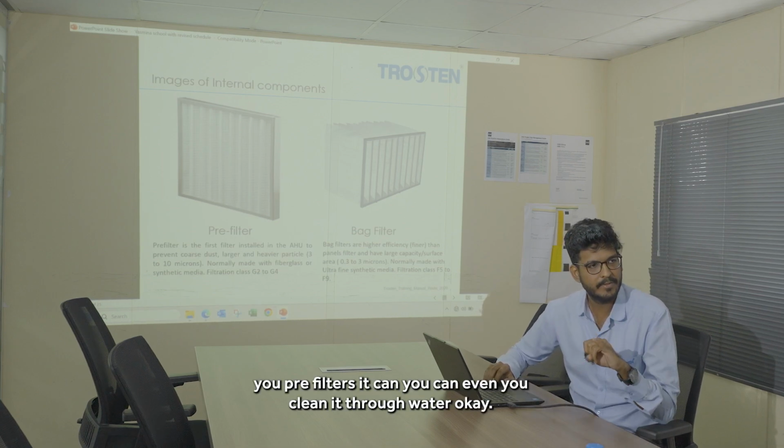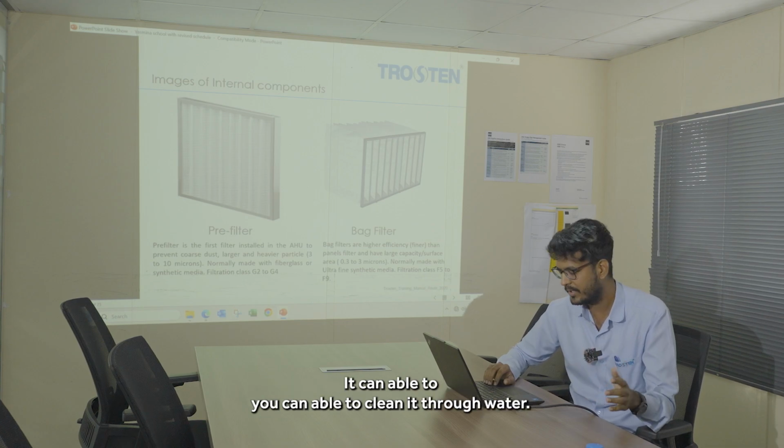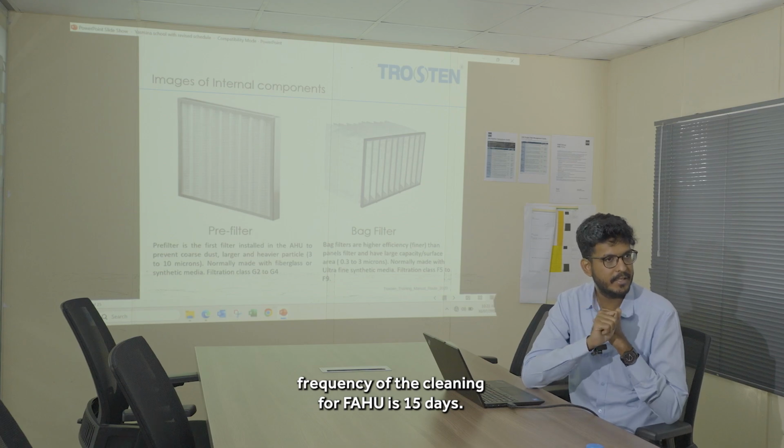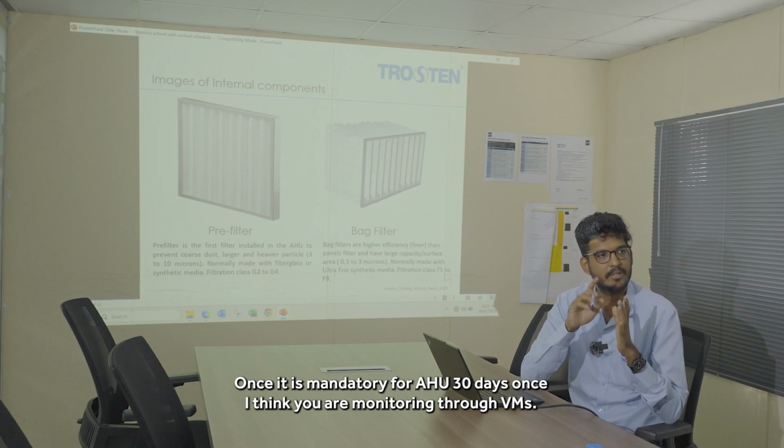Okay, as I told you, pre-filters you can even clean through water. The frequency of cleaning for FAHU is once in 15 days, it is mandatory. For AHU, once in 30 days.